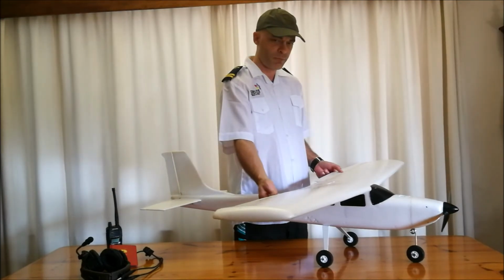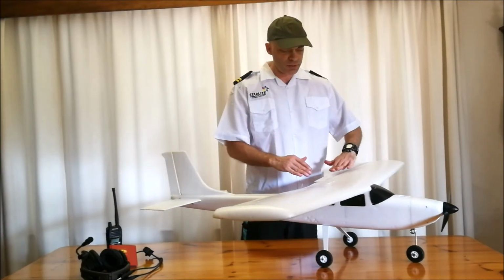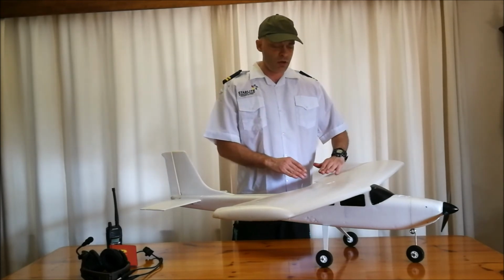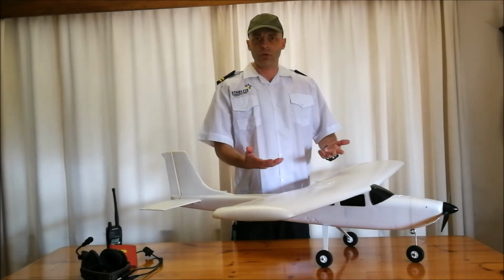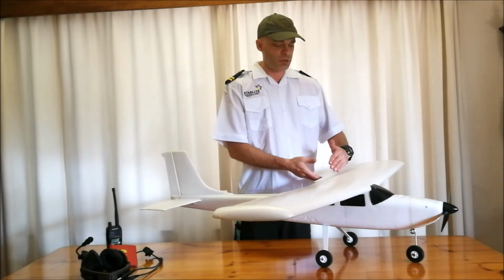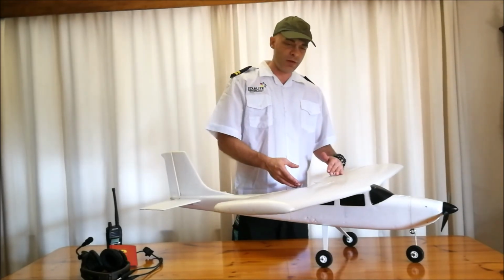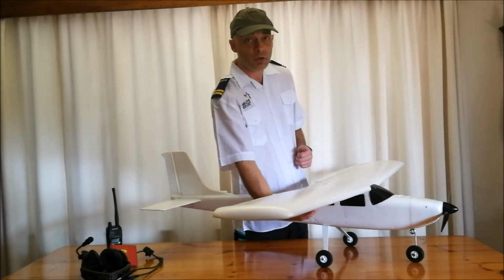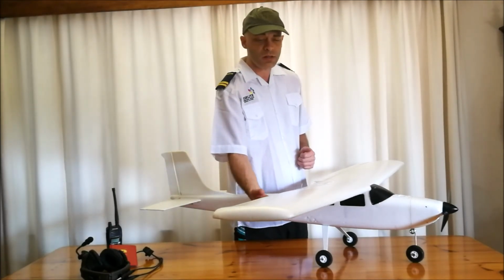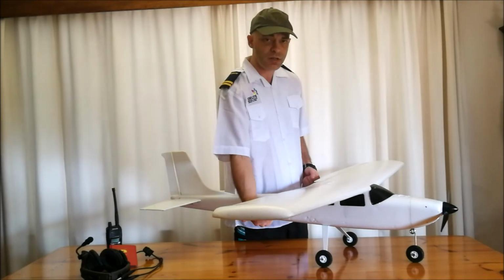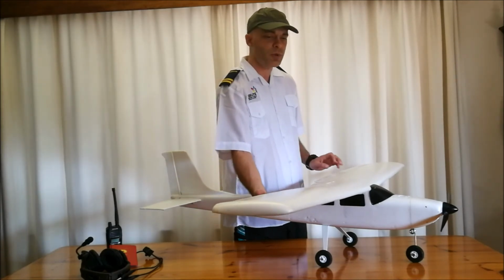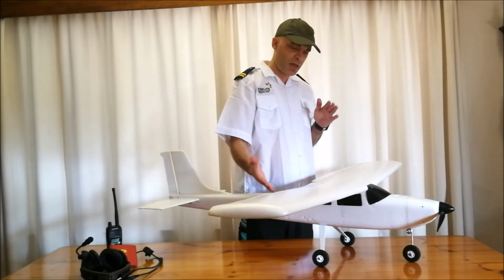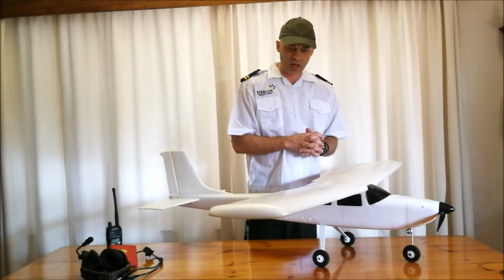So in this case, if this aileron had to move upwards and this one had to move downwards, the wind is going to hit against this aileron and, using Newton's third law, is going to push down this wing. On the other wing, the airflow will come at the bottom of the wing and hit this aileron because it's facing downwards, and that will cause this wing to push upwards. Okay, so that is how your roll motion is able to happen.